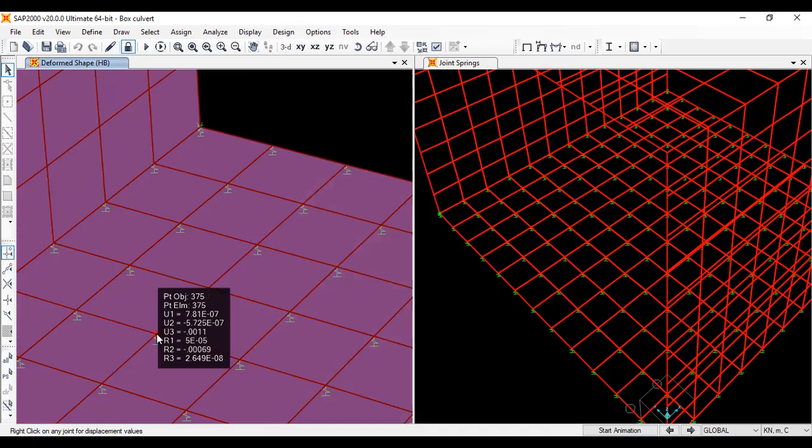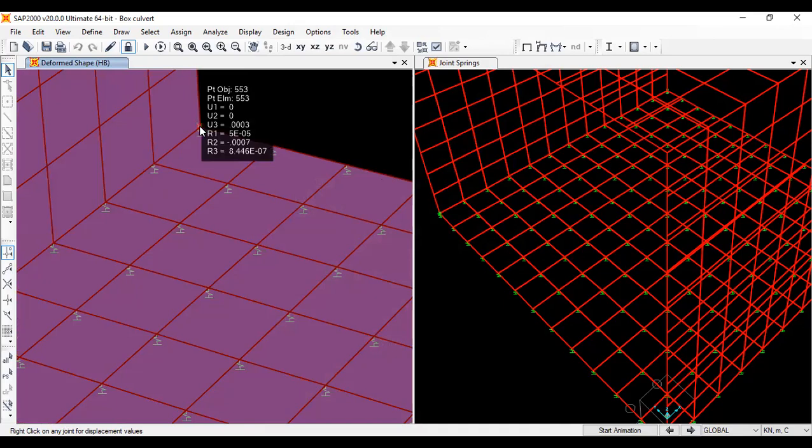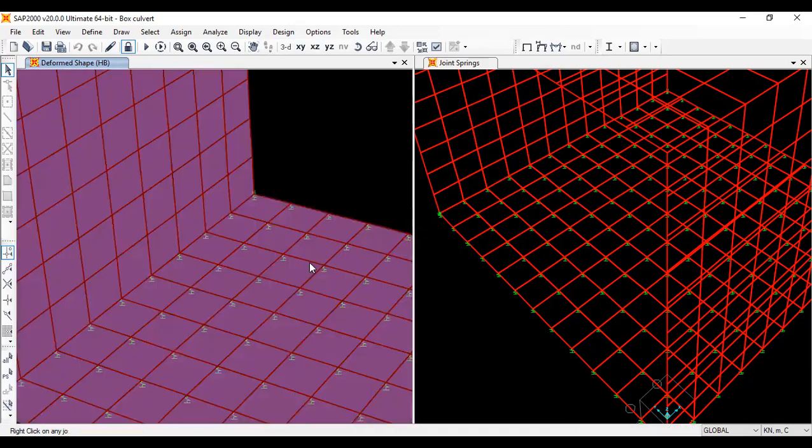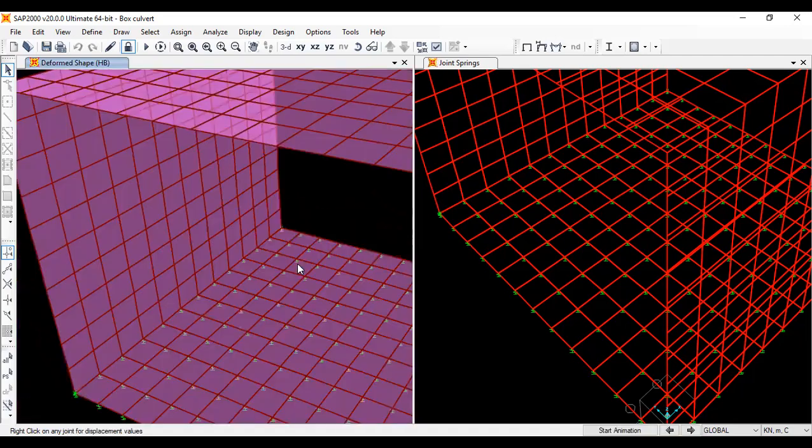If you apply a basic pin or roller or whatever to this, that is wrong, right? That will restrain the Z direction translation. Even at this point you have a displacement in the vertical direction that will give you the theoretical behavior of soil when a load is applied.